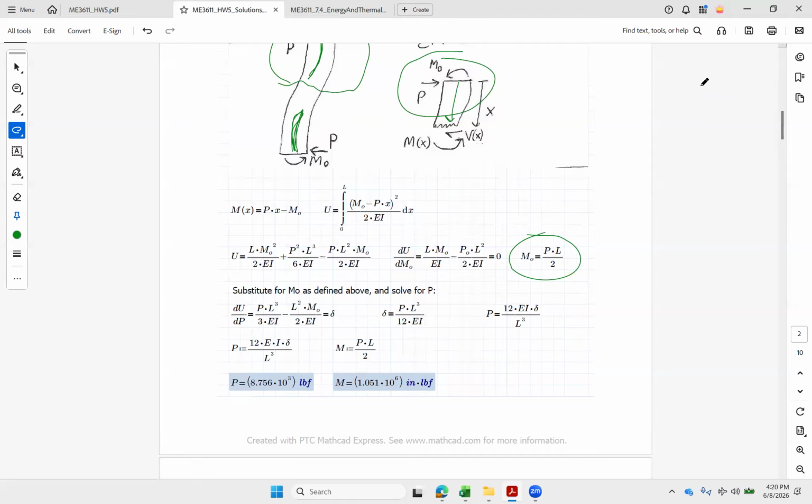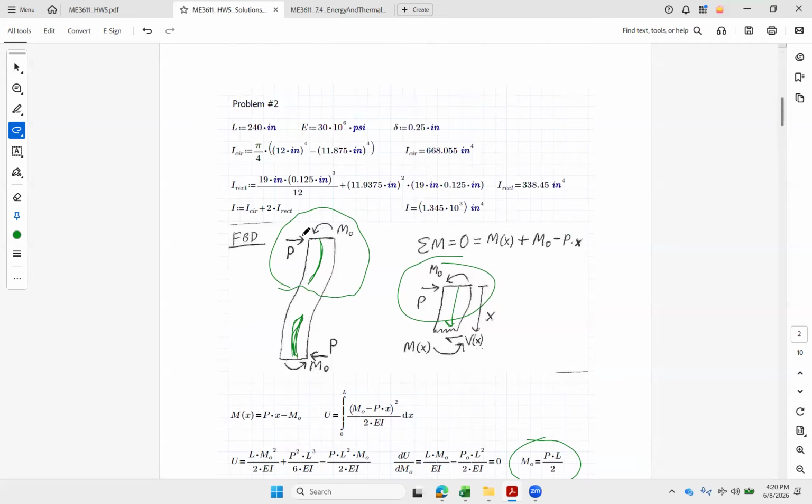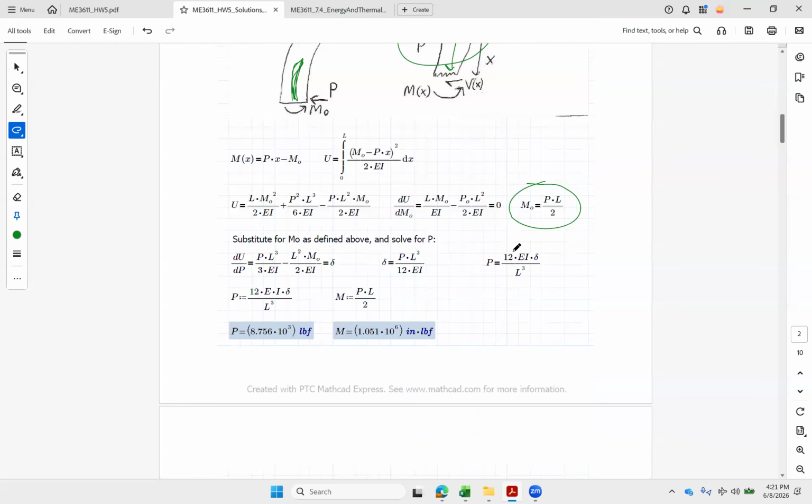Now, those are pretty large numbers. Remember that with a 1/4 inch of misalignment, what we're going to probably end up trying to do is we'll get some bolts in the misaligned area and then through the anchor, like we saw in last week's class, and then we'll start to tighten those bolts down, and they'll straighten up and they'll do the moving over. So we're not going to have to get a giant torque wrench and put 1,000,000 inch-pounds on there or push over with 8,700 pounds. This will be slowly applied by tightening down all those bolts. It'll slide it over that tolerance that we need. But we see once it's on there, it's carrying an awful lot of load, which is going to translate to some big internal stresses as well.